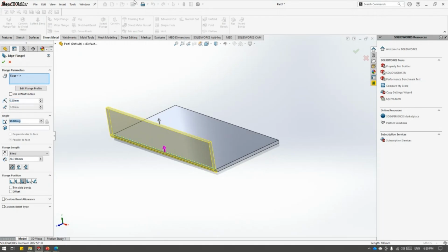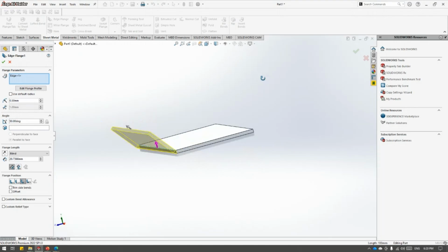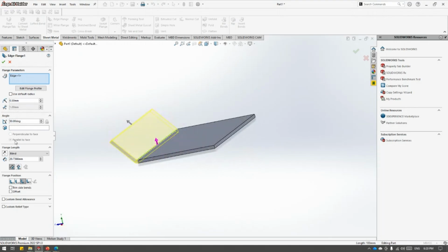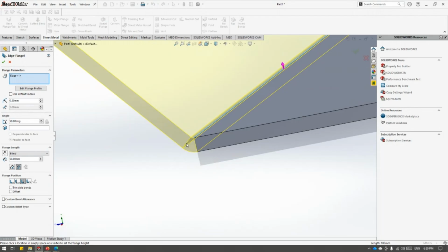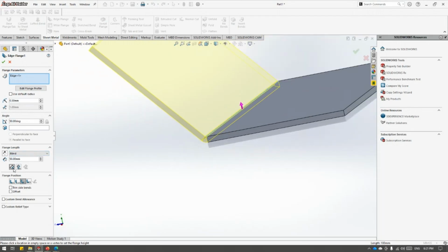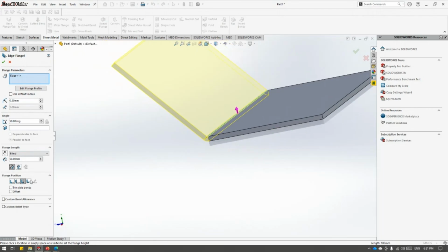And we can even change the angle to 50. You can update these, and here we have the extrusion, which can be increased from there. And from the icon you can pretty much see the inner virtual sharp and the outer. This is actually the length, from where the length will be starting. So it's from the edge, and it's from this extrusion point. At this point, it's 50 extruded, but for the other one it's from the edge, from the corner.